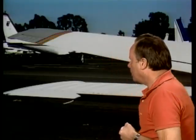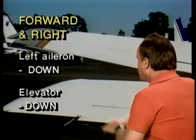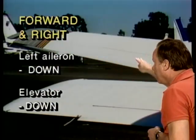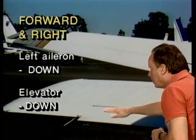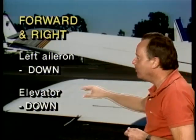So here we are moving the wheel forward and to the right. When we do that now, we're trying to turn the aircraft to the right, so this left aileron will go down. We're pushing forward on the wheel. We want to go nose down, so the elevator will go down. So if you move the wheel forward and to the right, the left aileron will go down and the elevator will go down. The FAA figures that's a good idea for you to know that, so when you hook up these controls, you do them right.